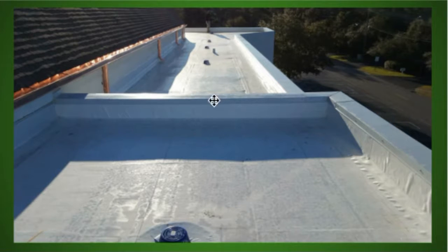So you do have to account for some sort of drainage from the roof. You don't want to make this like a swimming pool, so when it rains, it just fills up that portion. So you always have to think about drainage. But for our purposes, we're just simply modeling this as a flat roof. But if we were going to model it realistically, we would make it slant about 1 or 2 inches from one side to the other to a drainage system.